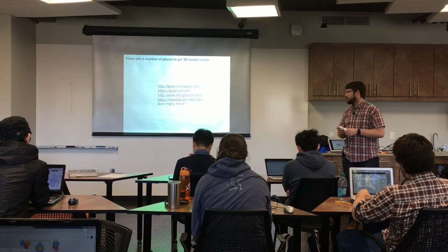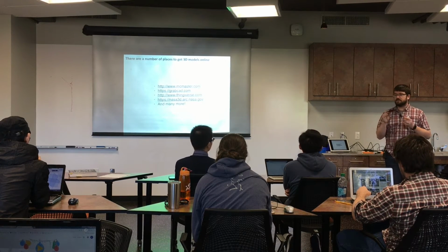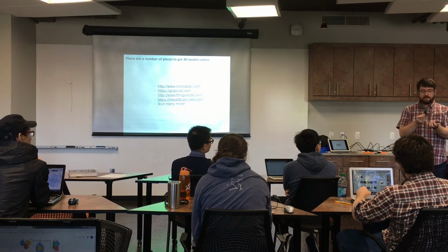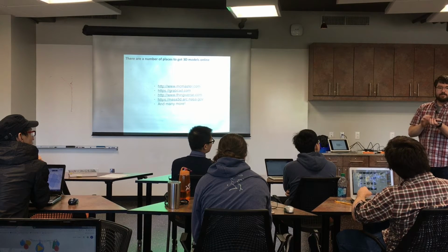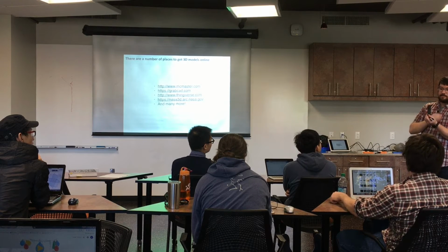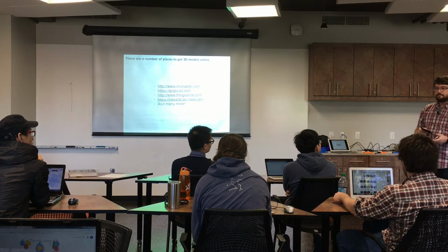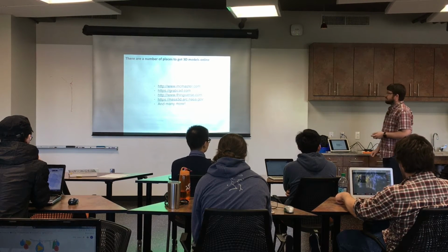And that one, actually, you would think that you would print it, like, let's say this is going to be our print of State College. You would think that you would print it on the printer bed like this, and you would build up the topography. But remember I said the Z resolution of the printer is a lot higher. So the best way to print that part to have the highest resolution is to print it like this, where the topography is sticking up this way, and get a much better quality print that way. And yeah, if you Google, there's tons of stuff out there.